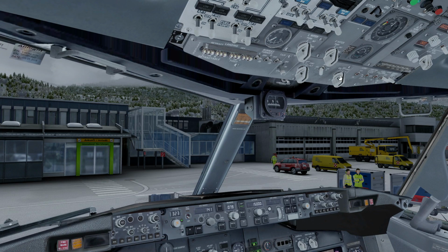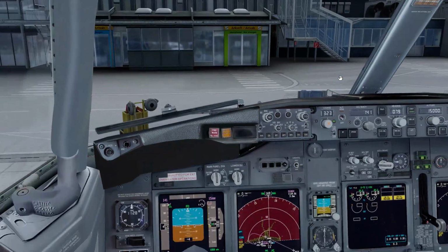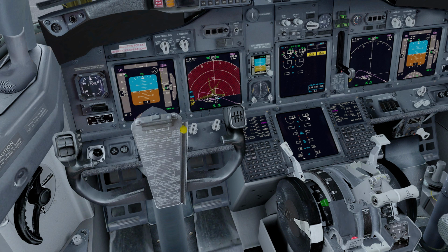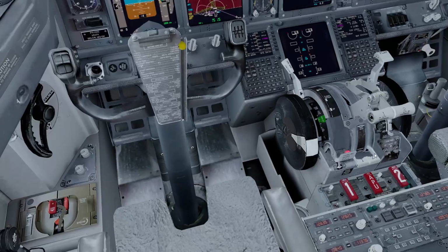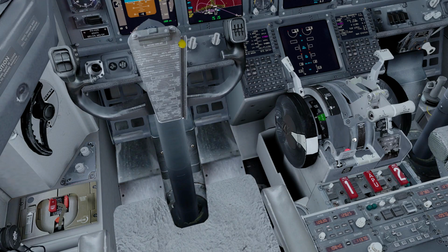We're going to move that switch to ground, as you can see, and this will start the ignition process. And basically what's going to happen, the engine is going to start up. The N2 value is going to be rising. At 25% N2 we're going to add the fuel and then monitor all the values and make sure that the engine starts up properly. Okay, so I'd say let's go. I'm going to tap the brakes and this should release the parking brakes. There we go.